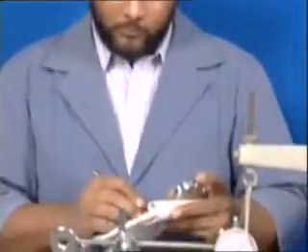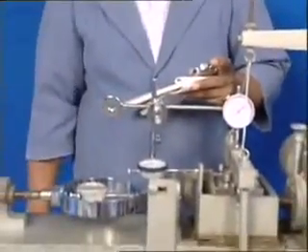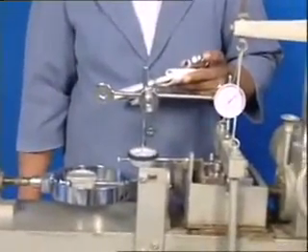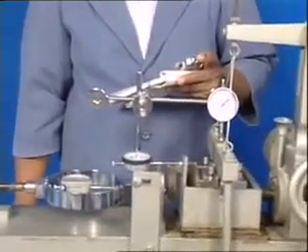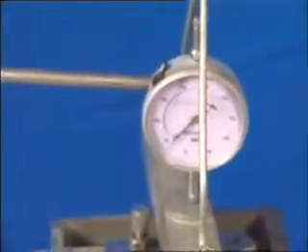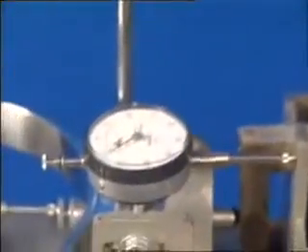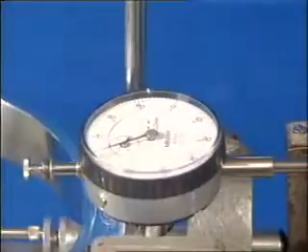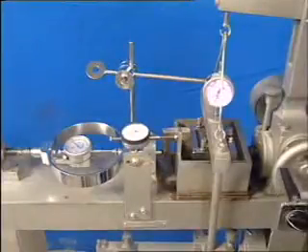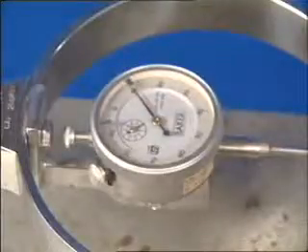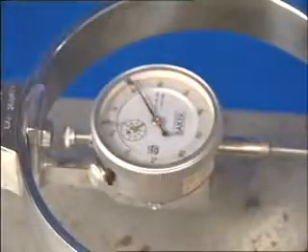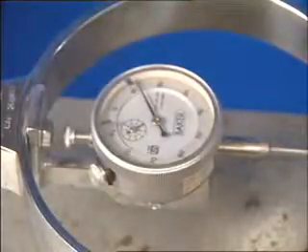Record the readings on the two displacement dial gauges and the proving ring dial gauge at regular interval of time. Continue applying the shear force till the specimen fails, which is indicated by a kickback of the pointer in the proving ring dial gauge. If such a failure does not occur, continue shearing till the specimen undergoes a shearing displacement of 12 mm.